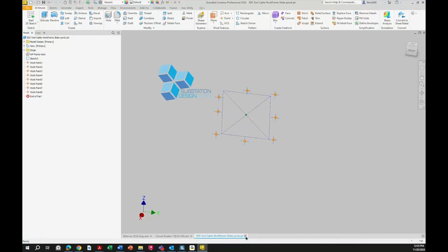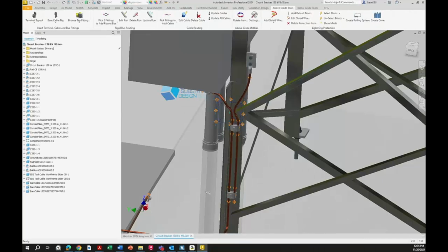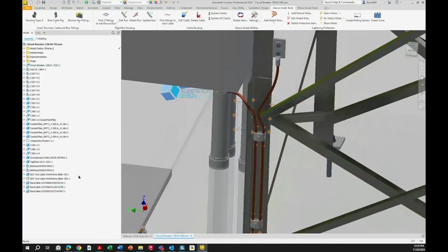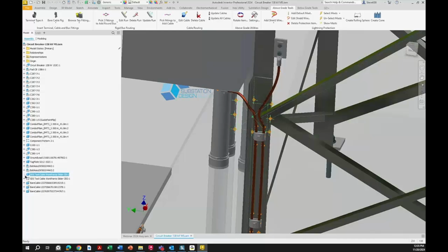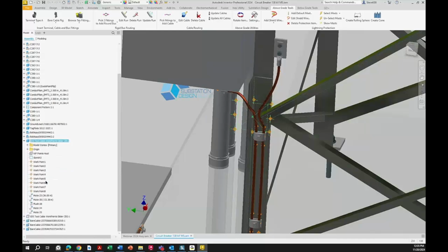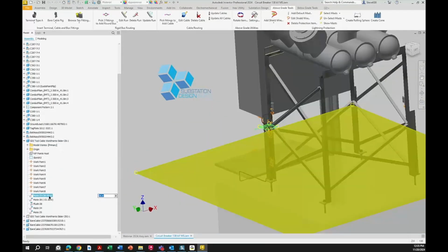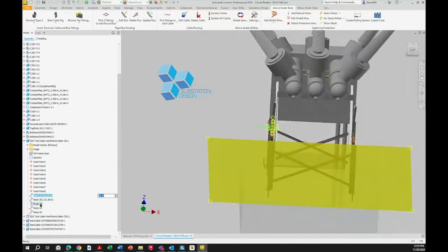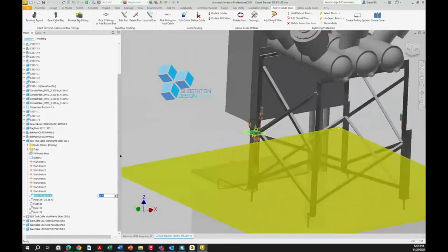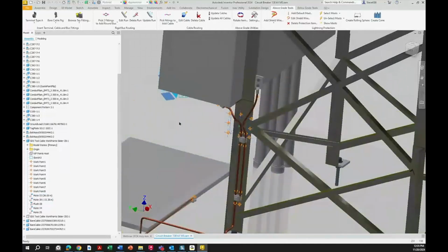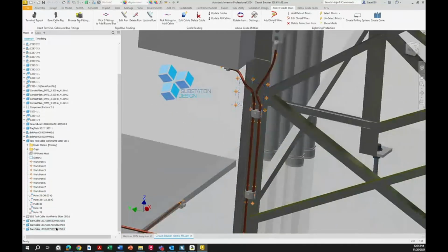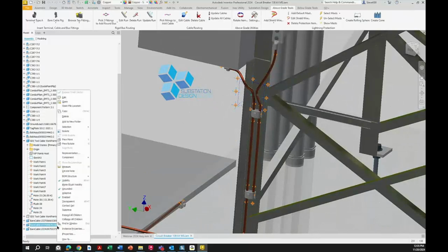So I'm going to come back into here. That's why I call it junk. And I put that tool in here. I just use normal Inventor practice to put that tool in here. I'm going to expand it. And I have my constraints. I constrained it here, here, off of that one. And I've got a flush constraint. Okay. So that's the way I placed it in here. So if I want to place these cables, I'm going to turn off the visibility of this one.